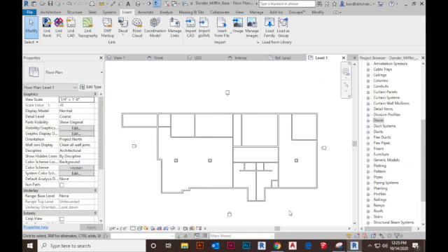You've also been provided a CAD document of the layout of these curtain walls to make it a little easier to place these curtain walls. On that CAD document, for the doors and exterior windows, you'll see generic dimensions giving us a width, a height, and in some instances, a sill height off of the finished floor. As we go through this exercise, I'll walk you through these steps of creating all of these openings in the interior and exterior walls.